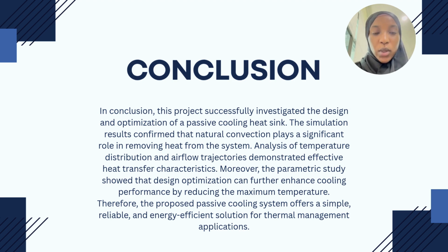So as we saw in the report, the CFD simulation showed that the geometry strongly affected the heat sink performance, and also that natural convection is the main cooling mechanism in passive heat sinks. It's a fact, and also the effective cooling depends on both heat transfer and the airflow pathways.